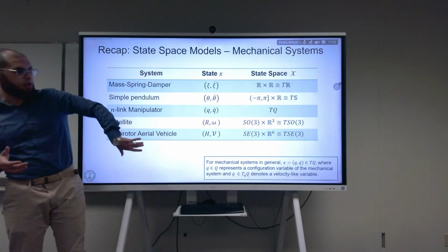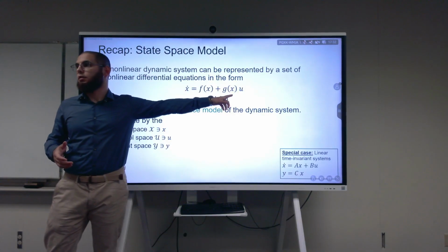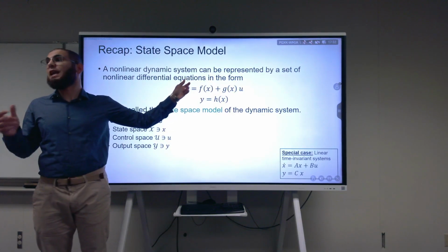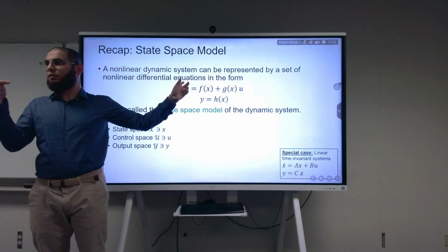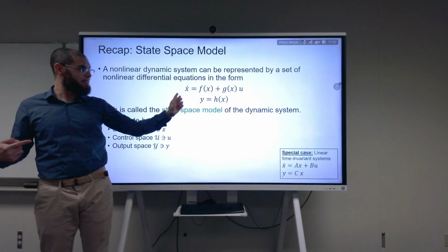If you go back to the equation of motion, the wrench will be the control input, exactly. And it will not enter an equation that affects the h dot. So for example, the wrench does not affect the h dot. H dot is an equation for the kinematics, right? The wrench affects the dynamics, so it affects the second equation.